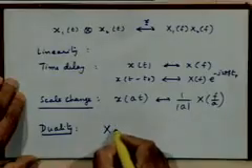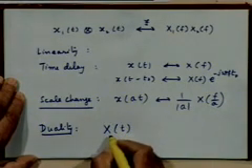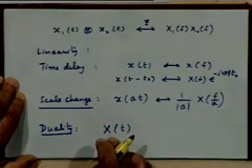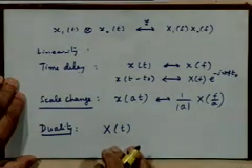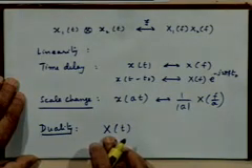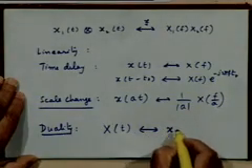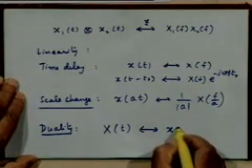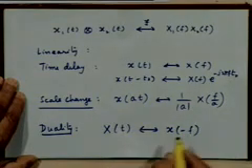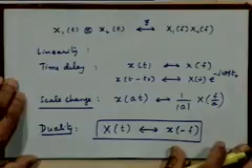If you construct a time signal which has the shape of the Fourier transform of the signal, of course, this will imply that x here is maybe a complex valued signal, then the Fourier transform of this would be the original time domain signal, small x, with t replaced with minus f. So this is the duality result.